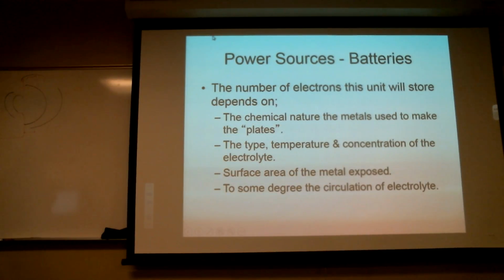However, there are a lot of applications where we use a battery like that. When we do, we start the engine and we charge it right back up. We don't deplete it very much. On the other hand, there are some cases where we want a fairly low amount of current over a long period of time, like in our motorhome or in our boat, running the lights and the toaster and whatever else. That's a very different mission profile. So we might want that battery to go through a long state of discharge and then be recharged, a deep cycle, versus a high cold cranking amp shallow cycle.